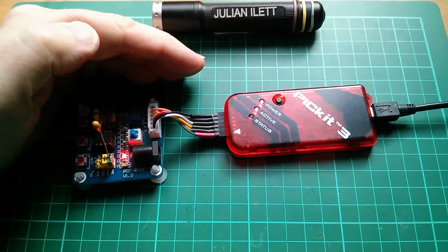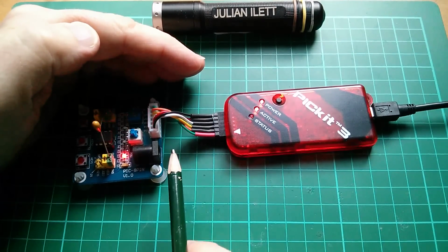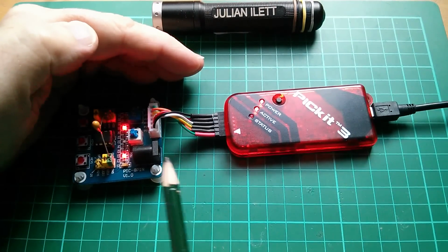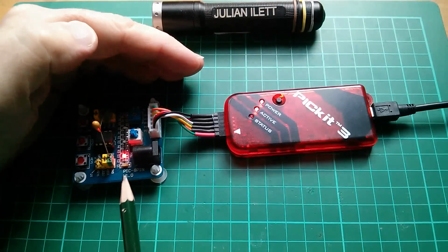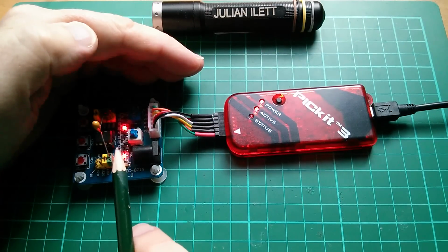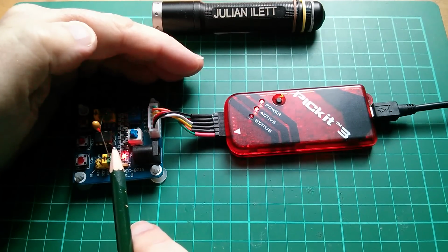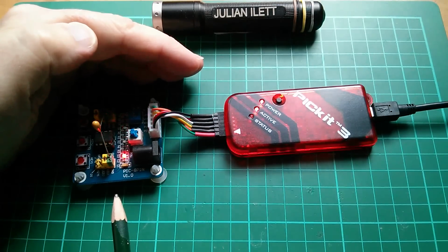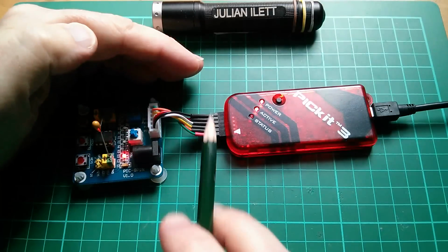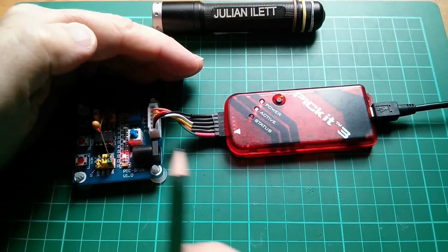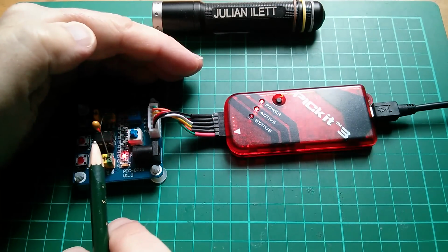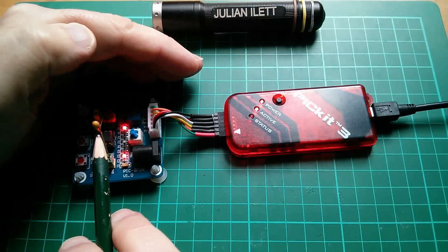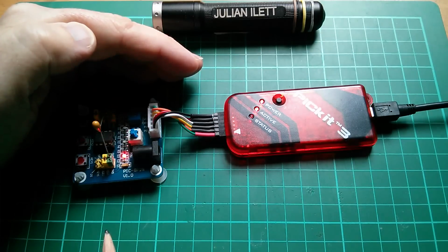So that's it. That's LED Blinky. We've written our first assembly language program. We've controlled the GPIO. We've controlled the TRISIO to set the microcontroller pin to be an output. It defaults to being an input. We took a programming approach to create the flashing loop, but then we had to take a systems approach, in fact an electronic engineering approach, that capacitor, to finish the job in time.